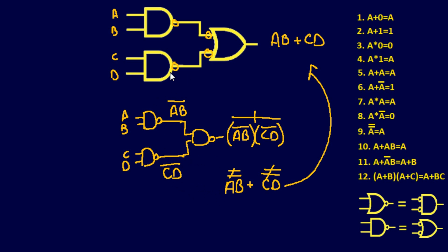And by doing this, this will actually require 2 chips, because it requires 2 AND gates and 1 OR gate, whereas this particular circuit only required one chip, which is a 7400 chip. So if you remember your old digital classes, they actually had to use some of these weird chips and all these digital gates. Well, this one only required just one of these guys.